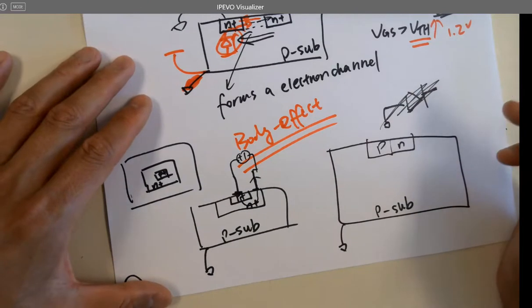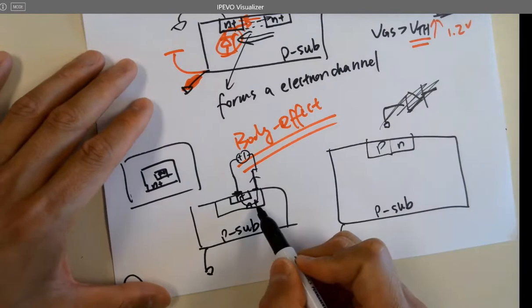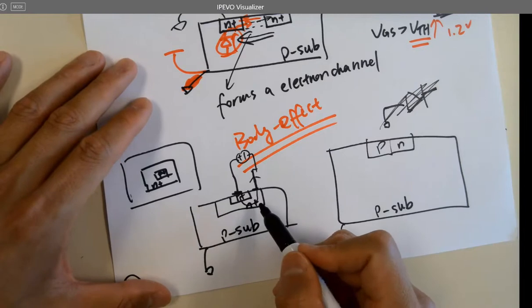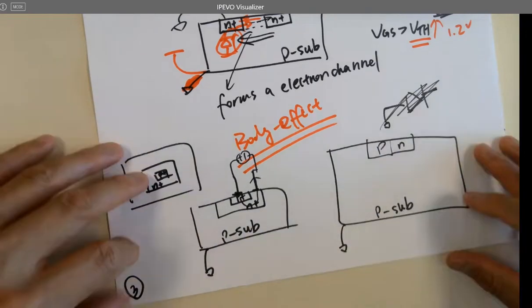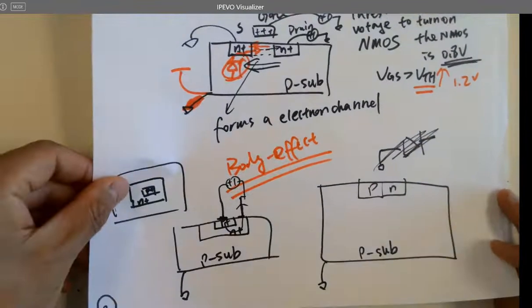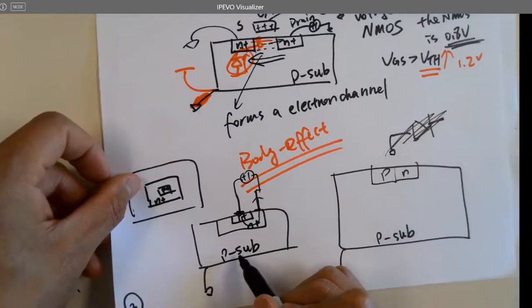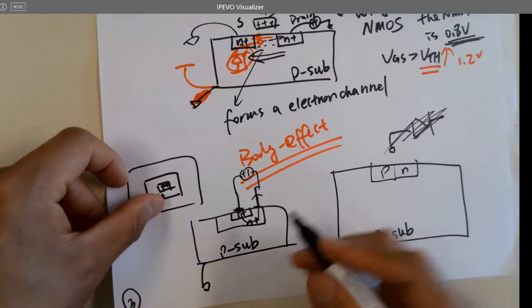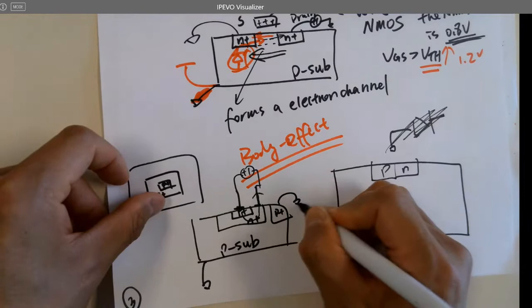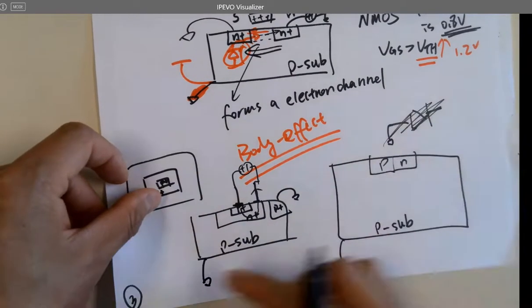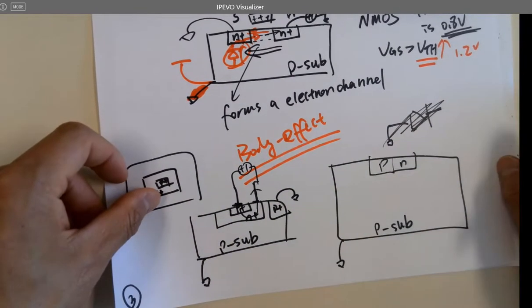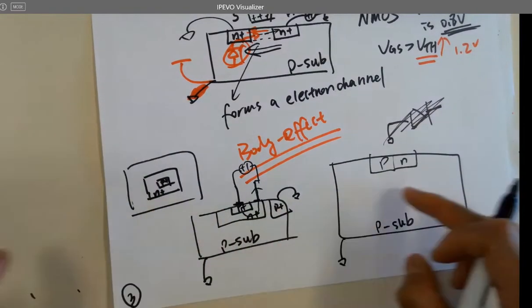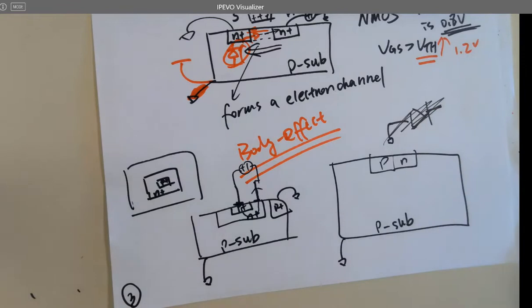So you are using N plus to do what? All right, that's how I make a diode on the wafer. And because this is a substrate, all the integrated circuits are fabricated on the same side. If you have a P plus here, grounded, let's ground the entire P sub. But sometimes you need multiple P pluses everywhere, not just one little P plus.